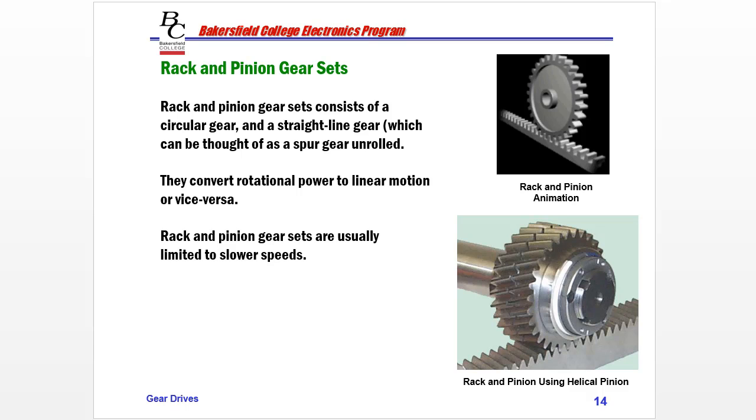Well, that's what this is. There's a shaft tied to the pinion, and it's tied directly to the steering wheel, and as we turn the steering wheel, then the rack moves back and forth, and that is tied to our tie rods that are tied to our wheels that turn our wheels left and right.